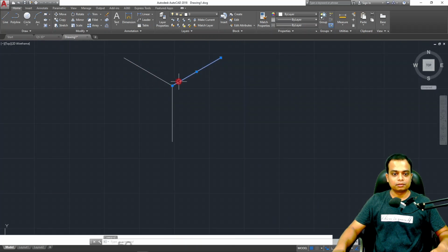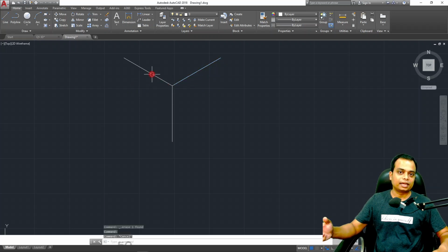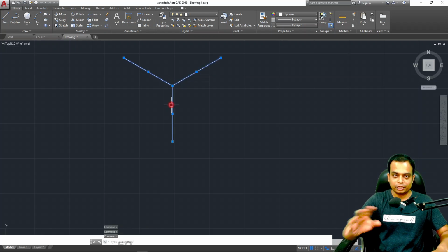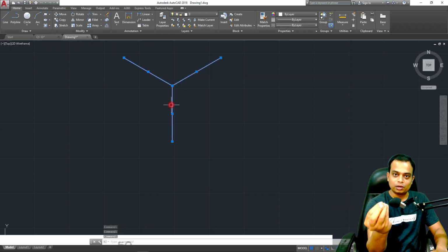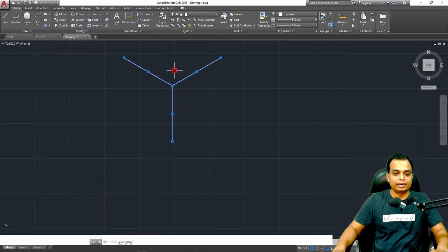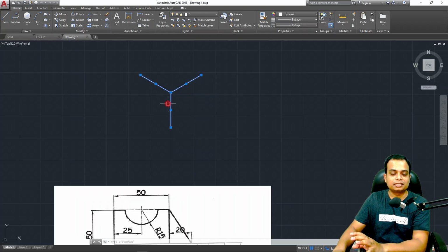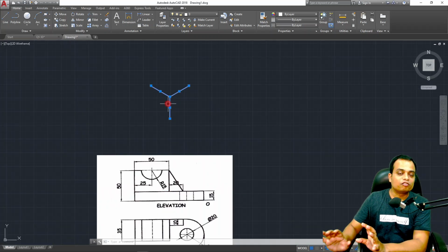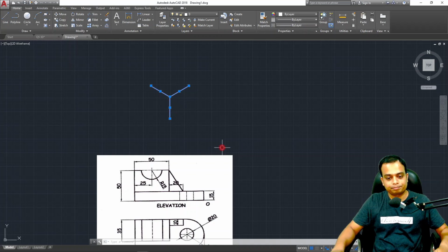Okay, what is this? If you just make the horizontal, this is at an angle of 30 degrees. This is also at an angle of 30 degrees. These are what we call the isometric axis. All of them are equally inclined to each other. Iso means equal. What is that equal angle? That happens to be 120 degrees. Okay, between them, 120, 120, and 120. Please make these set of axes, as they are going to help you orient your mini drafter accordingly.